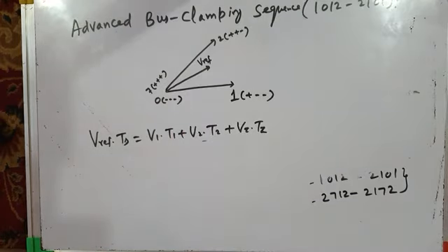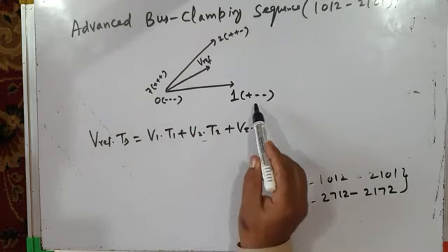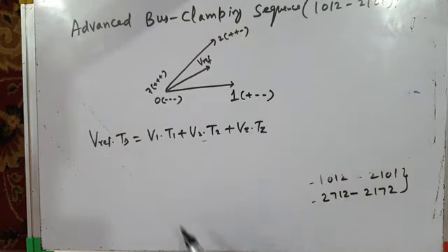However, we know that at a particular instant, when a particular space vector is applied, say null vector 0 or active vector 1 or active vector 2, there is always an error voltage vector. That is always an error between what is desired and what we apply, and that results in stator flux ripple.